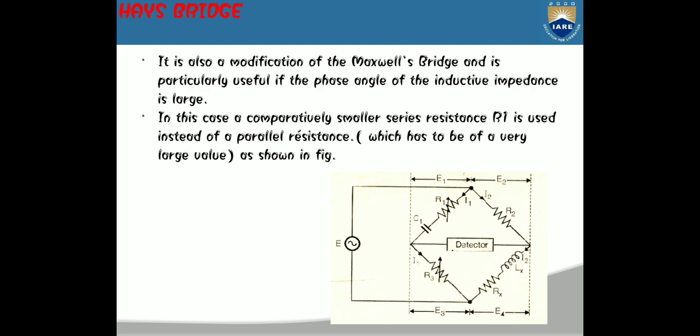A practical issue in construction of the bridge is mutual inductance. Two inductors in propinquity will give rise to mutual induction when the magnetic field of one intersects the coil of the other. It will reinforce the magnetic field in that other coil, and vice versa, distorting the inductance of both coils.